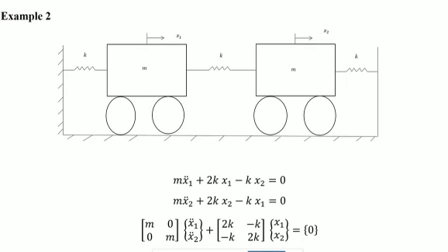Now you see, when both of them keep on moving, there is no repetition of the motion. So the number of cycles performed in unit time is zero because they are moving. So the first natural frequency is a zero frequency, and the first mode shape is a rigid body movement, there is no end to it.